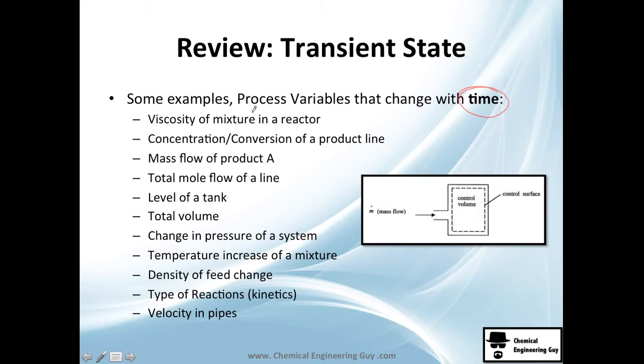So many times if you're starting with a reactor and, let's say, A turns to B when you heat it, so you put heat here, maybe you're going to experience viscosity changes, not only because the reaction is changing a substance, but also because you're adding heat, which normally implies increasing temperature. So the viscosity may change. So we don't want that, or it depends on the case.